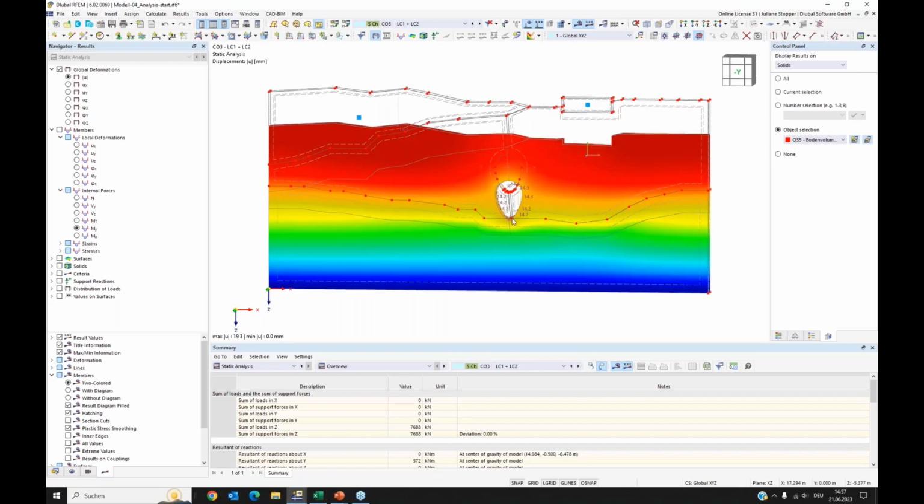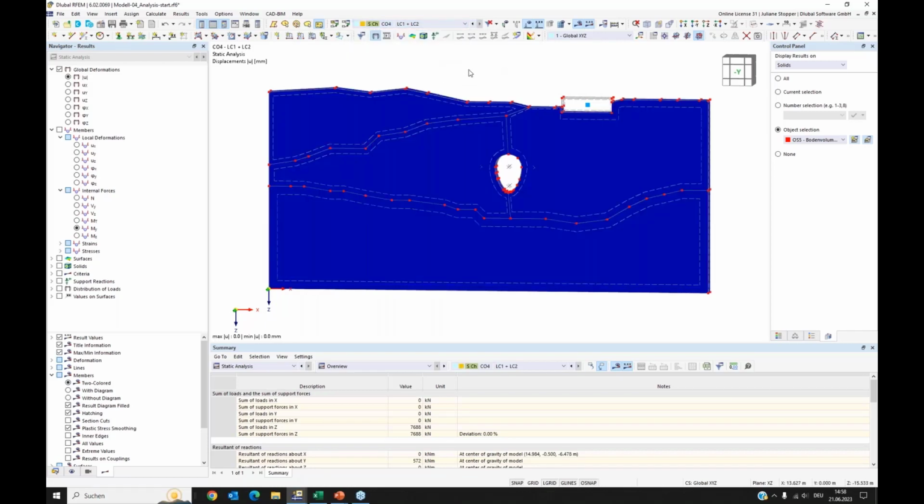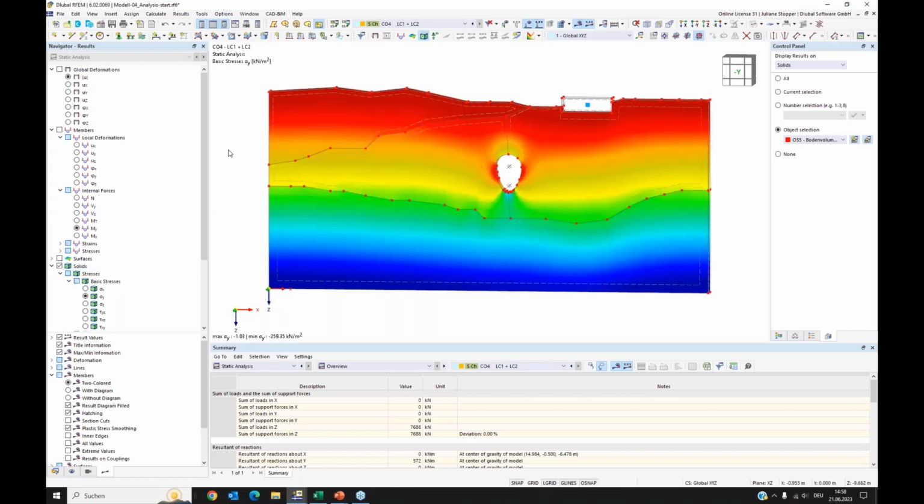This deformation we don't want to see in our results. That's why we reset it to 0, because when I start my construction of this building, for me there's 0 displacement at the beginning of this load case, or load combination. So that's why we have this copy where we said reset displacement shall be used, and we can see it worked well. The displacements are 0. But if we have a look at the stresses, we will see that we have stresses. And we can also compare it with the previous combination, and we see it's the same.